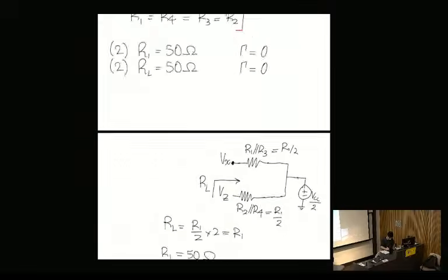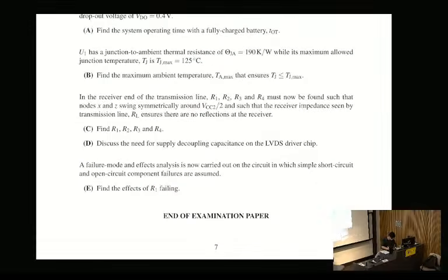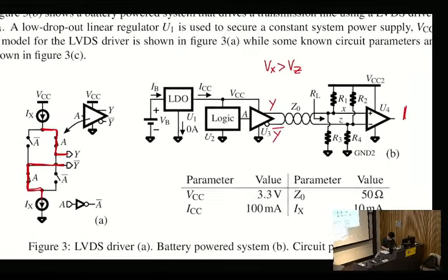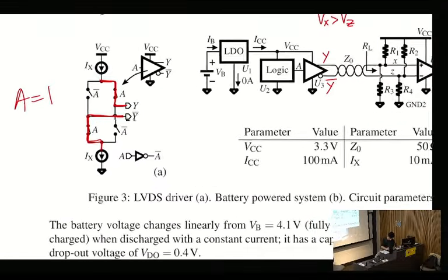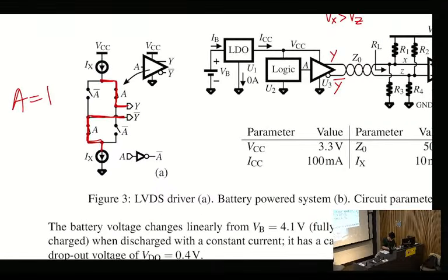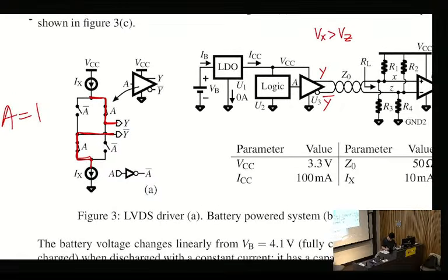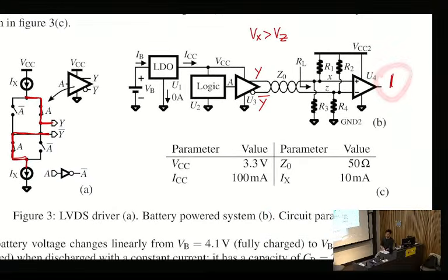So we spoke about what the point of the circuit was here, right? We said if A equals 1, then the output here should be 1. So what we need to do now is consider, is that still going to be the case with R1 open?